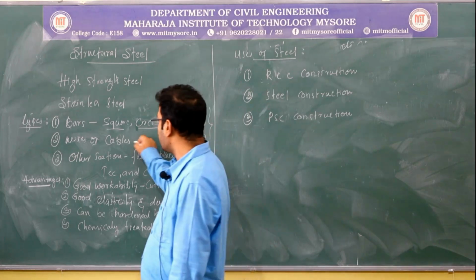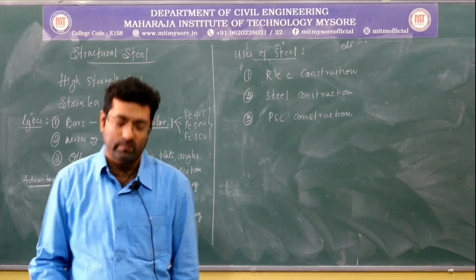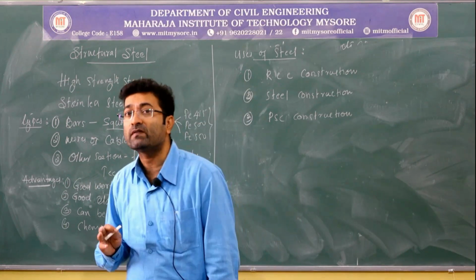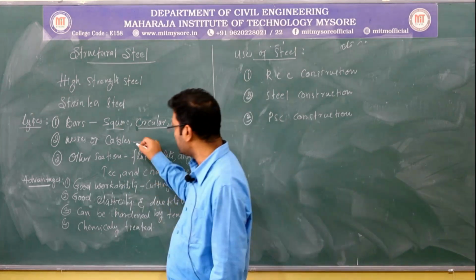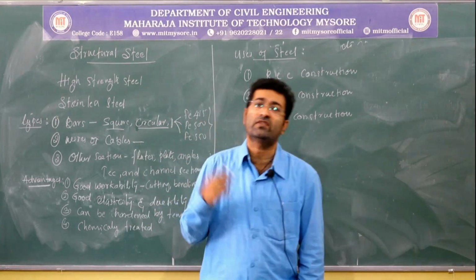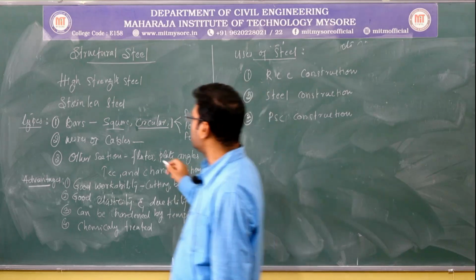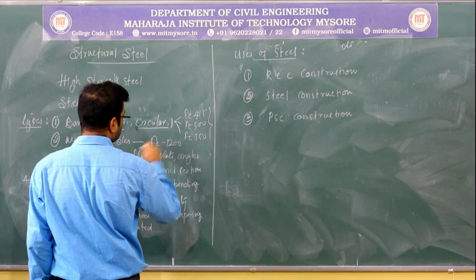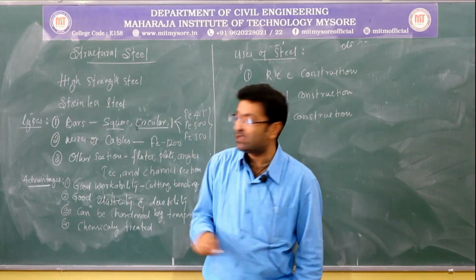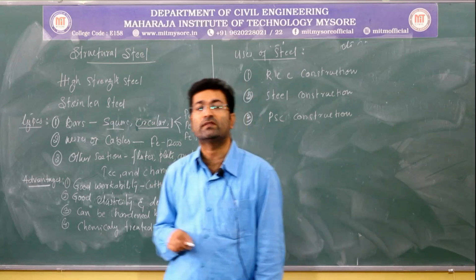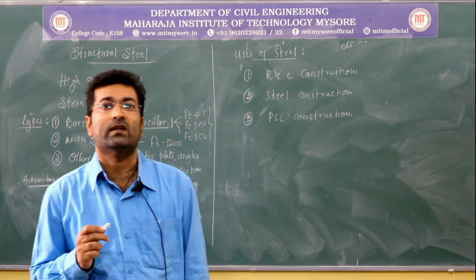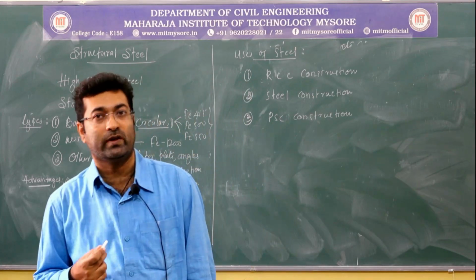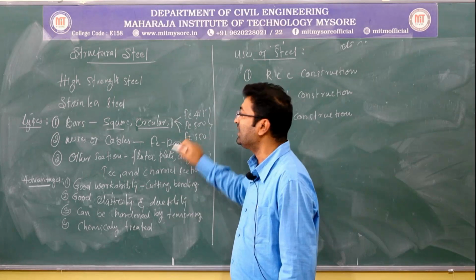And the steel wires and cables are basically used majorly in the PSC member. The steel we use in PSC members will be of high strength. These wires or cables will be somewhere around Fe 1200 grade. That is, the yield strength of these steel bars which we use in the PSC members is higher, 1200 newtons per millimeter square.